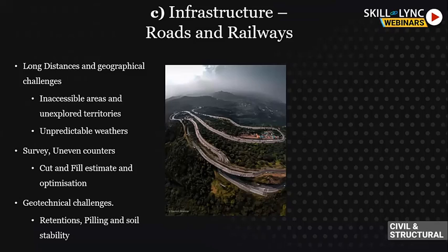The major geotechnical challenges that you would see are the retentions, because if you are going through the hilly areas, you would be cutting certain portions, and the retention of that cut would be a challenge, again in the scope of the structural engineer. It would be piling that will be required, and then the soil stability. Each and every part of this word itself is an engineering challenge. So piling is a different design, the soil stability is a different design. Each can be achieved by multiple ways, like the diaphragm walls, the piles, and the rock anchoring into the rocks and all. So all these knowledges are really required.